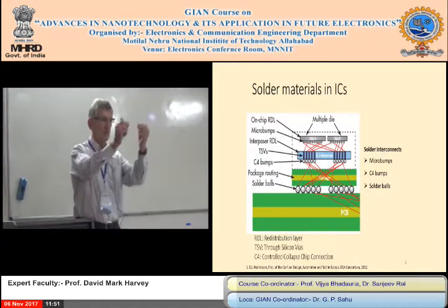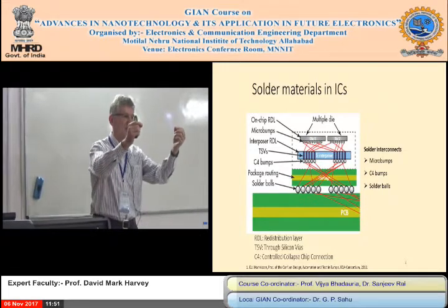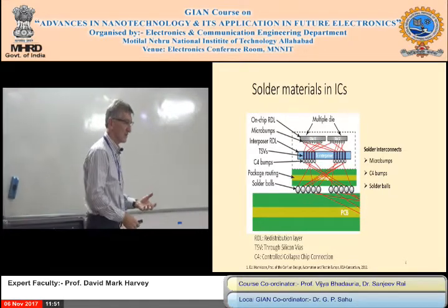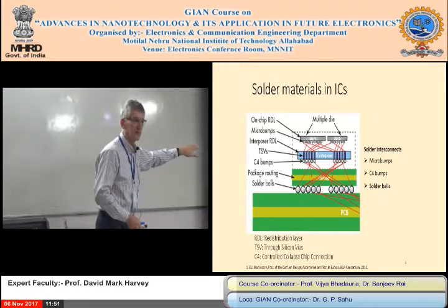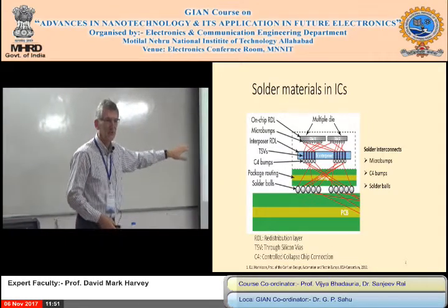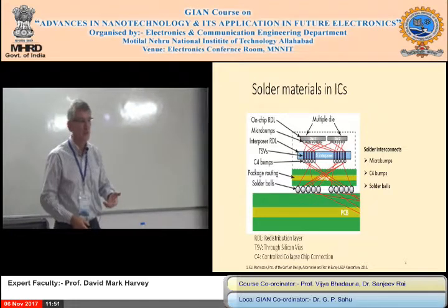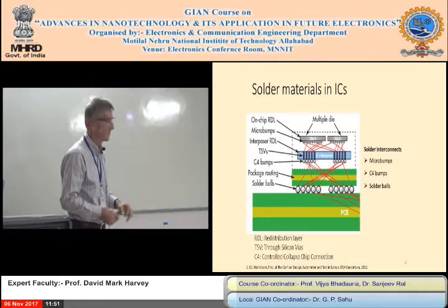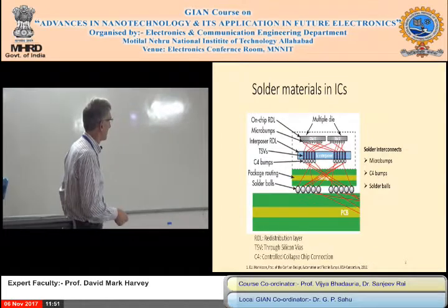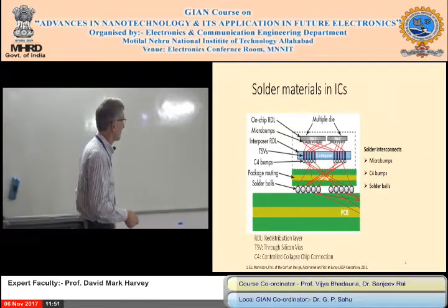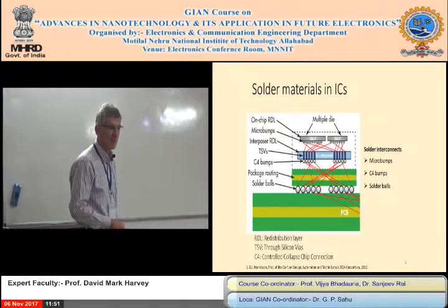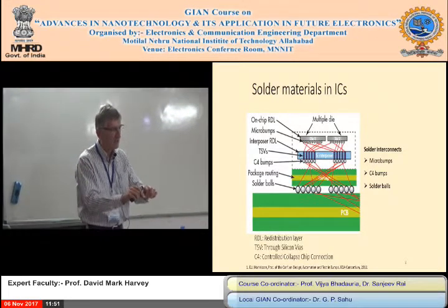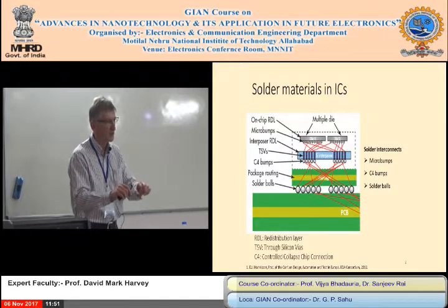You can get your probe, put it onto the solder joints, and they're quite big, 0.1 of an inch in those days. So easy to test. These things, impossible really to test, which is why I'm going to teach you new ways to test this week. You can't get a probe in there, as we'll see later on this afternoon. So these spacings might be 0.5 millimeter. You can probably, if you're clever, just put a probe on with a sharp point and see what's going on if you want to do some testing on the board.